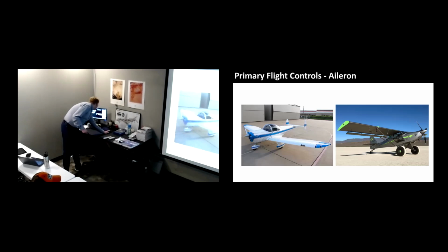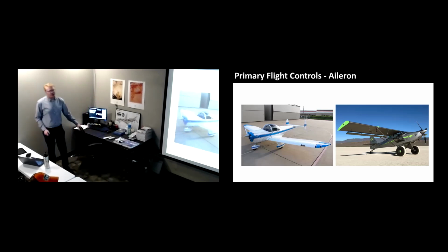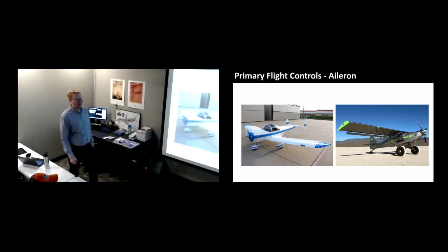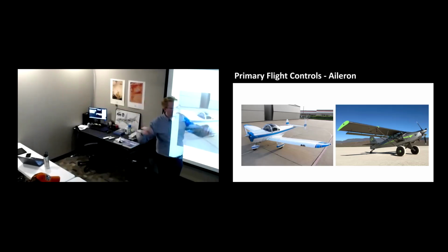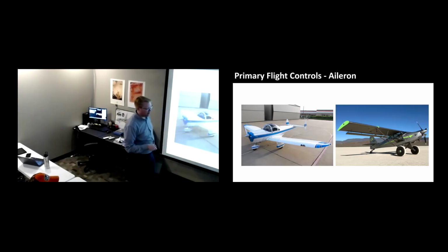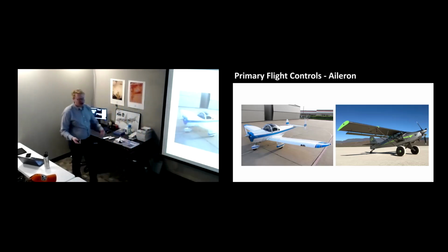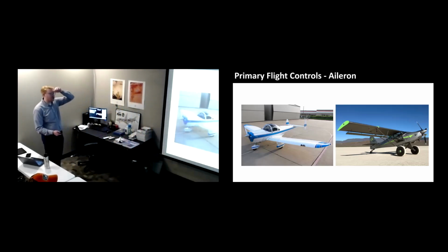But it's designed to take off in a very short amount of runway. Correct. So all of your short takeoff and landing capability airplanes will have different functions. You can also notice it has a big camber, meaning a big bulge over the top of the wing. That airfoil would not do well at high speed. This produces a lot of lift, so as you get faster, you get a ton of drag. You need a lot of power to overcome that drag. So this airplane is really good for slow speed flight.